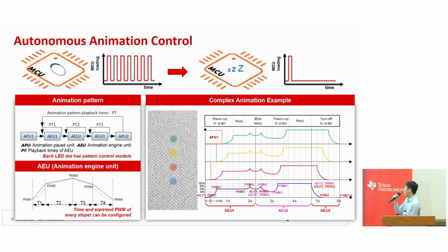With these 3 groups of register configurations, we have all the abilities for your customizations or design to do whatever the RGBW indicators or animation transitions per your design requirement. By the way, the demo on the LED light ring is just accomplished by this new LP5813 device.